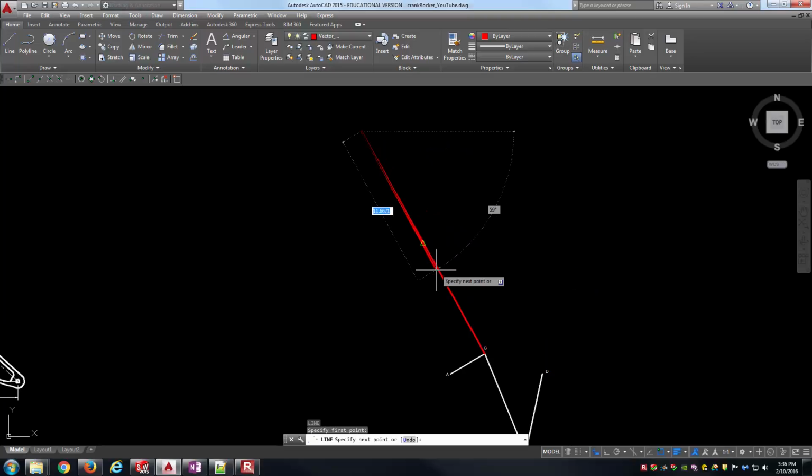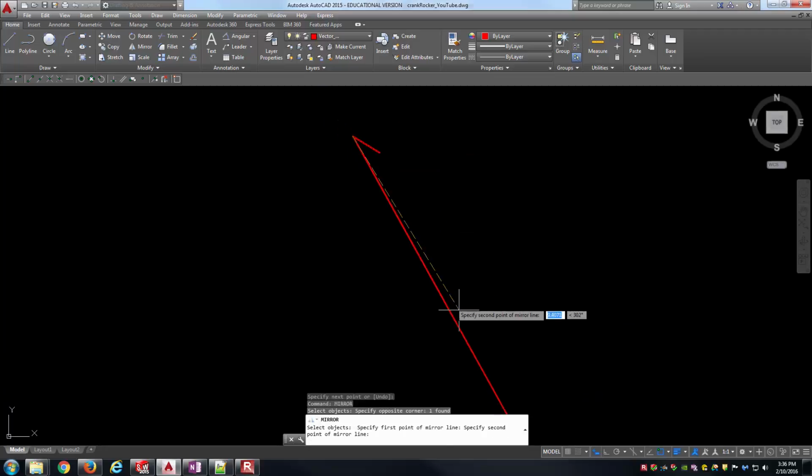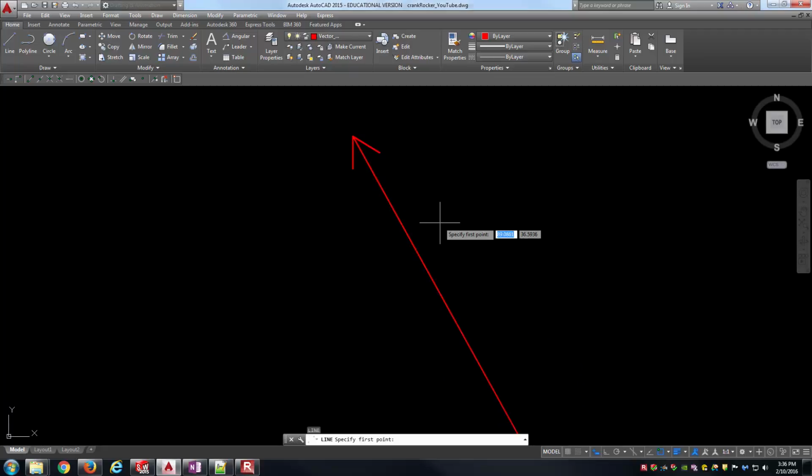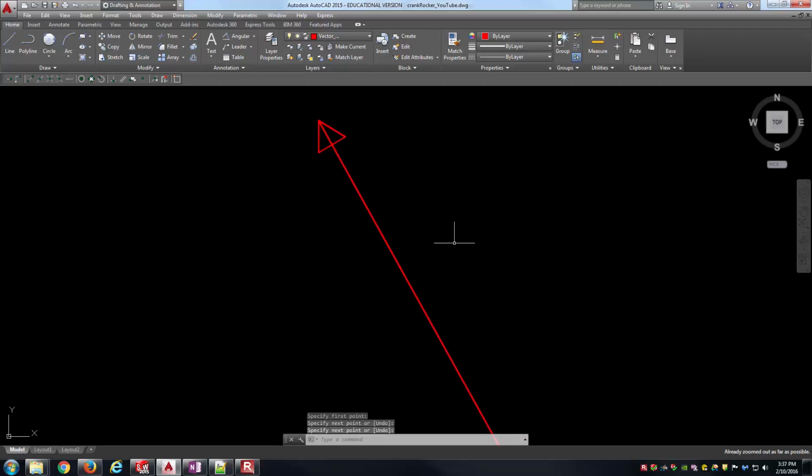And so here what I'll do is go ahead and make a little arrowhead here. Let's just say it's 1.5 length for the head, 30 degrees for that angle, and I'll mirror it across here. The reason I'm doing this is just to keep track of which end's the start end and which end's the terminal end of the vector.